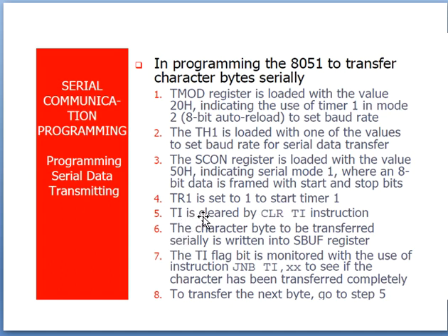So that's why before execution you need to clear it. Then the character byte to be transferred serially is written into the SBUF register. So the data which you want to transfer to the external peripherals has to be taken into the SBUF register. Then the TI flag bit is monitored with the instruction JNB TI, to see if the character has been transferred completely.